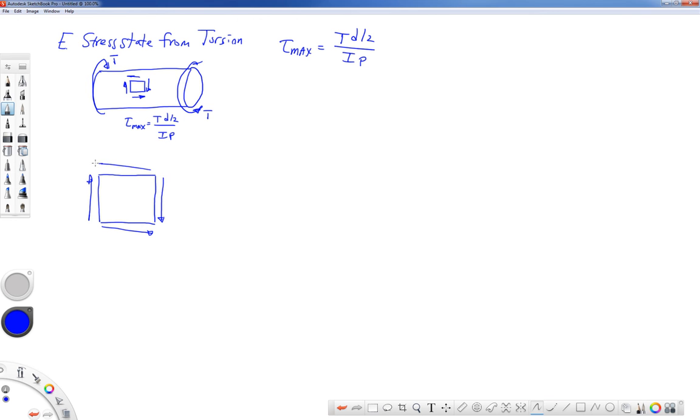Where I have these shearing stresses, I'm just going to label them tau. All right, so I want the stresses at an angle. Let me change colors. And imagine there's an angle running through this block. It could change. It could be 0 degrees, where this red line is straight up on the left. It could be 90 degrees, where it's straight across on the top. But we're going to use the notation that the book uses. They call this angle from the vertical to that slant the angle theta. We want to find out what the stresses are on this red slant.